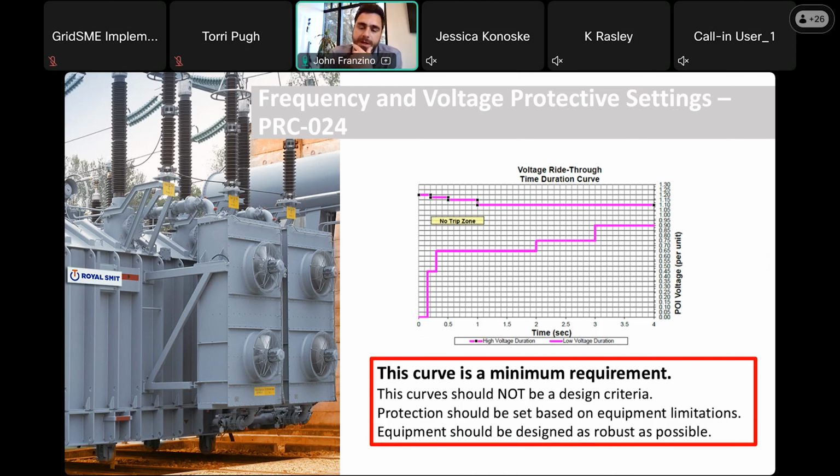The other thing that's occurring as it relates to IBRs and voltage and frequency ride-through requirements, and I won't get into too much detail right now, is the concept of momentary cessation in the inverters. It's one of many different areas in which this new inverter technology doesn't really fit within the box or the words of previous regulatory constructs and reliability standards.